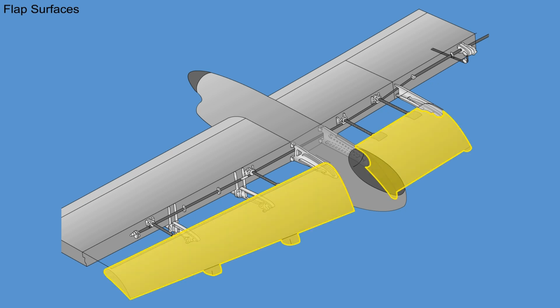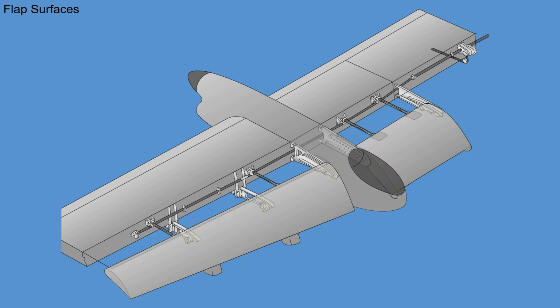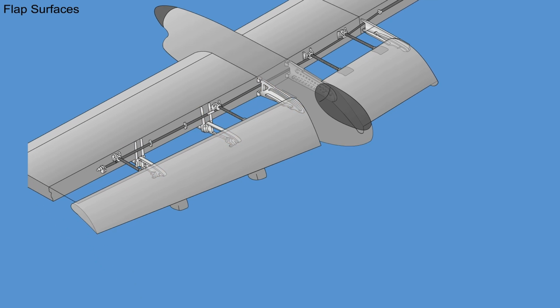There are 2 large flap sections on each wing. The inboard flap is supported at each end by 2 hidden tracks, one on the fuselage and the other on the inboard side of the engine nacelle. The outboard flap is supported by 3 tracks, one on the outboard side of the engine nacelle and 2 at intermediate stations below the wing. Each flap is a single slotted high-lift Fowler action type flap.